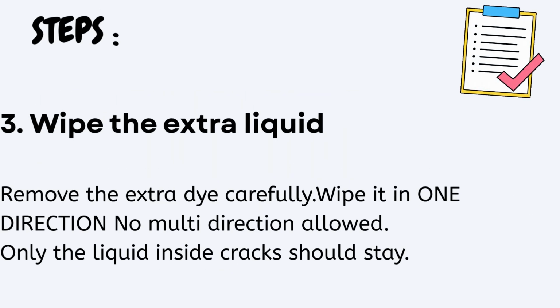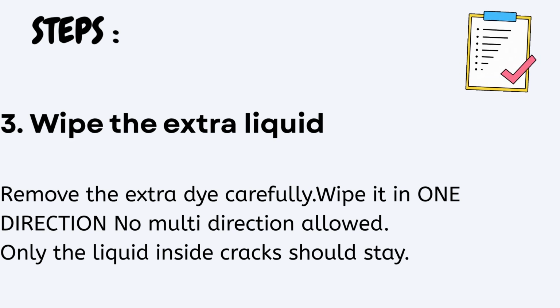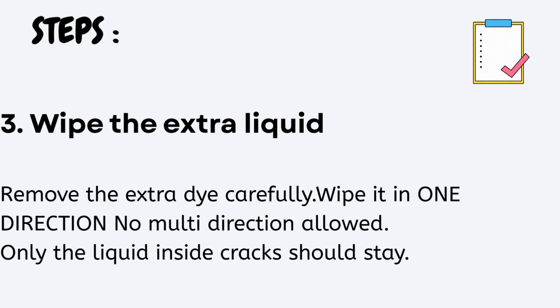3. Wipe the extra liquid. Remove the extra dye carefully. Wipe it in one direction, no multi-direction allowed. Only the liquid inside cracks should stay.